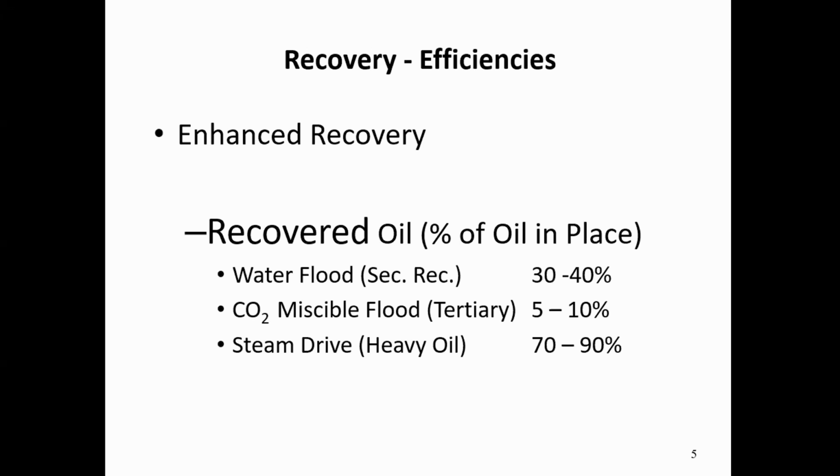Yes, sir. Then, if the primary is not covering everything, people think about the next step, which is secondary. Step number 2. And in secondary, there could be 2 methods of EOR. If somebody asks you how many methods of EOR we use in secondary recovery, the answer is only 2 methods. What are they? Water injection and gas injection. Remember that. There is nothing else in secondary recovery. Either you do water injection or you do gas injection.